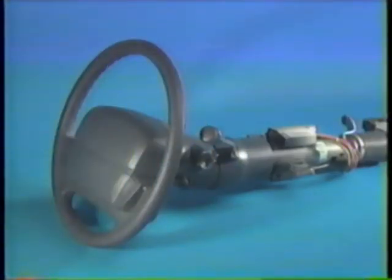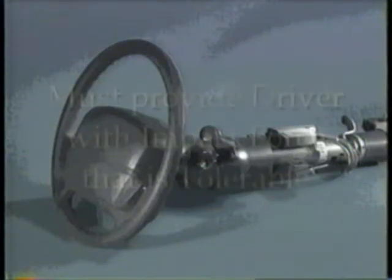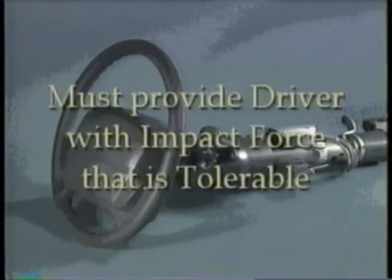Energy-absorbing columns have to serve 2 functions. First, they must stop the steering wheel and column from being pushed toward the driver as the front of the car crushes. Also, the energy-absorbing column must provide the driver with an impact force that is tolerable when he or she strikes the steering wheel. At the point of impact, the column should maintain the load on the driver's chest to a survivable level, and then deform under that load to protect the driver.